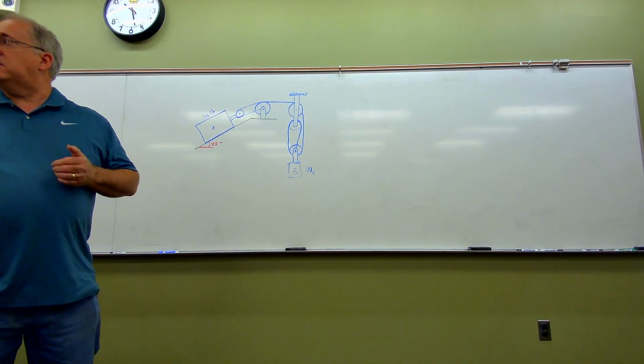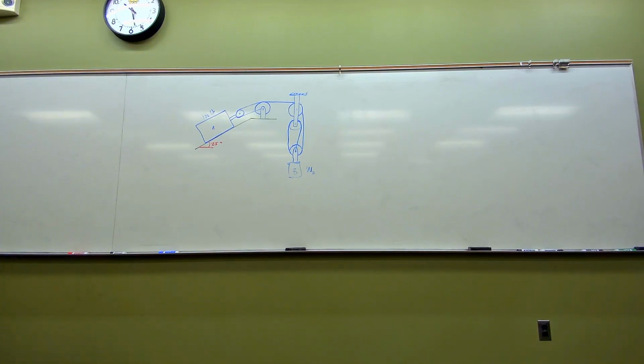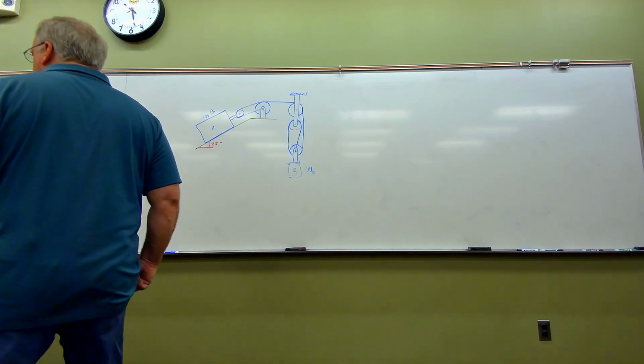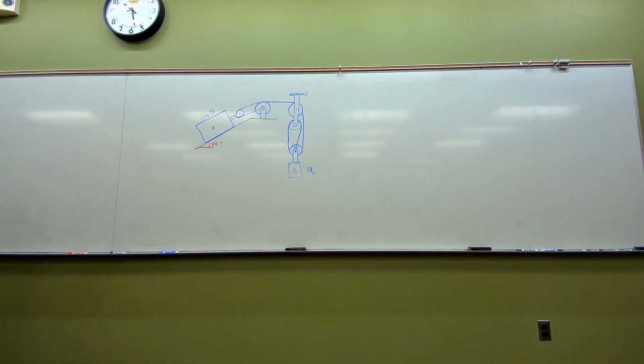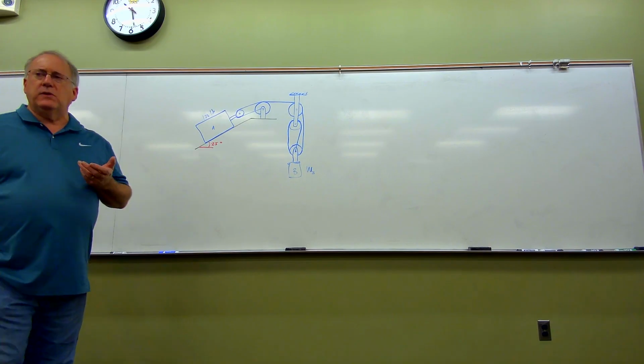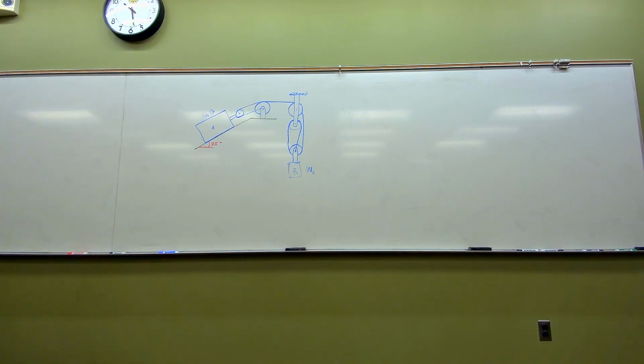As we've moved into chapter 6, all we needed to understand was how to show those frictional forces. And there are probably two really important things that fall out of that. Number one, frictional forces are actually not adding an unknown to our problem. They're adding a proportionality relationship to the normal forces that are already there. In other words, frictional force is nothing more than the coefficient of friction, the proportionality constant, multiplied by the normal force. So we're not adding anything new.